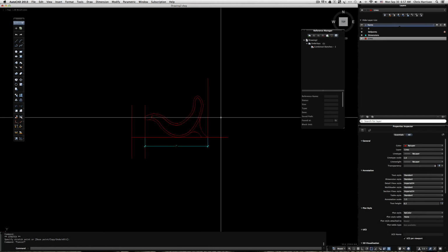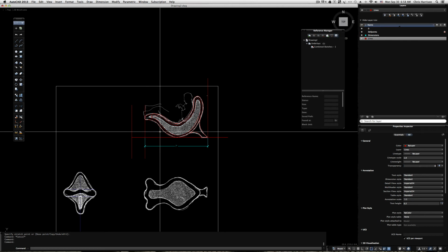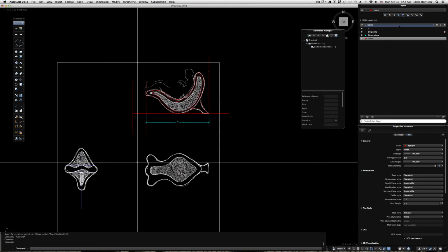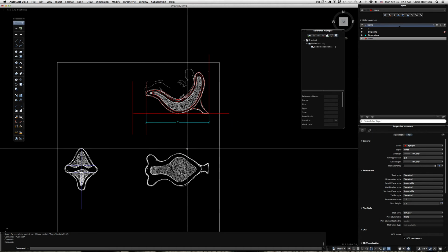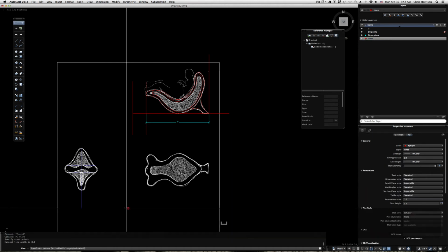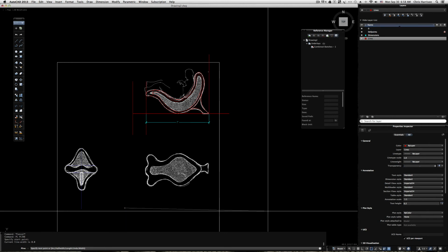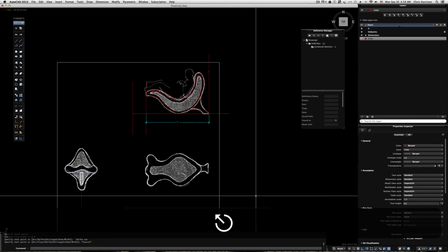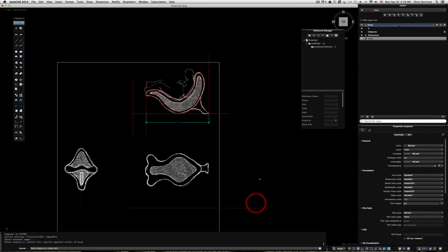Okay. Now, there are more pieces to this puzzle, right? So let's turn back on our drawings. Now you have this one shape drawn, so it's important that when you're doing a technical drawing that all the parts coincide. So what I like to do then is to, let me create a line here, let me turn back on my ortho, and I'm going to extend these lines to it, right? Because this is my width. I know that this is the width, and I know that's right.